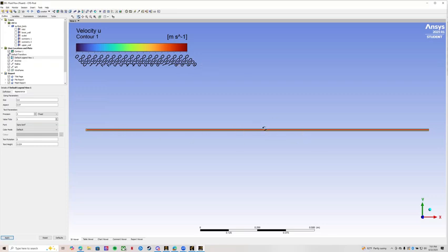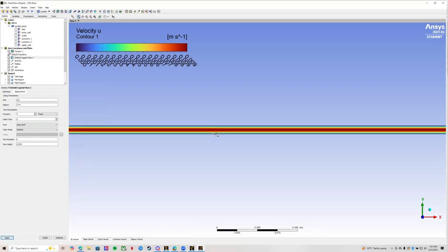If we zoom in, you can see how we go from being at a very low velocity relative to zero, as we get closer to center, we get to that higher velocity, and then back to that lower velocity, because we have those no slip conditions and stationary boundaries.